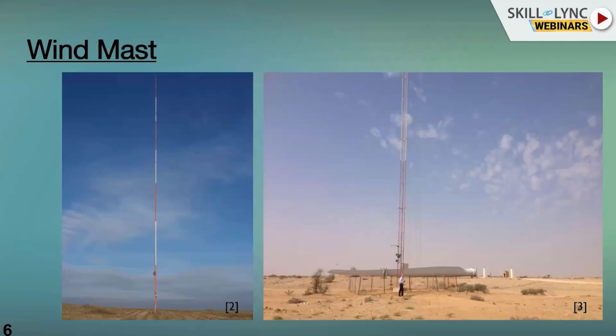The anemometer measures the wind speed at the particular site. The wind vane shows which direction the wind is coming from. We also install the temperature sensor, to measure temperature for a minimum of 1 year, along with solar radiation, vertical wind speed, barometric pressure, and relative humidity. These parameters we have to measure at the particular site.